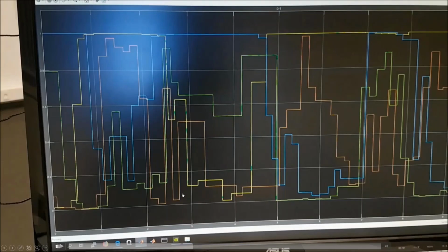So it's one camera but segmented, and soon I will move it over, and then you can see the probabilities calculated for each segment that we then use for the computation of the direction. So if you wait a little bit, this is the view of the drone from where we are sitting. If we move over here, I'll pause it for a second. You can see the 4 different probabilities, and you can see that yellow and blue are high.